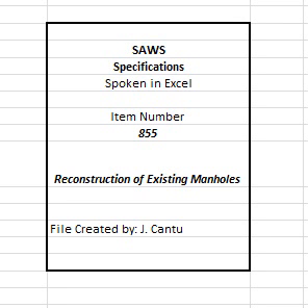D. Each component or separate piece of the manhole structure shall be marked with a tag or stamp that clearly and legibly identifies the coating manufacturer, coating product utilized and date of installation. Tag and/or stamp shall be placed in a location that can clearly be seen within the manhole or structure. 9. Other approved materials are located on SAWS website under SAWS APL. The list is periodically updated and should be checked by contractor prior to start of construction.